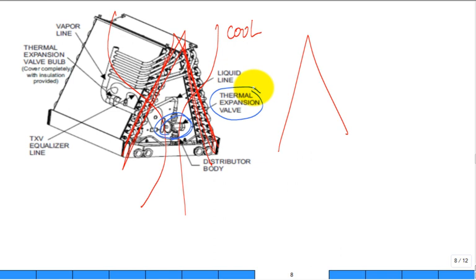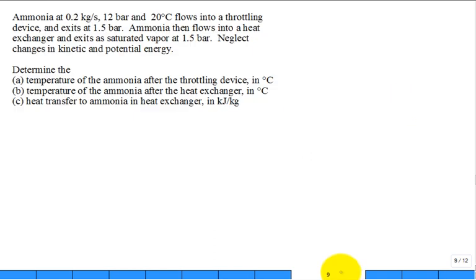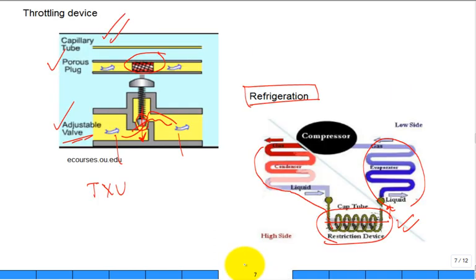Anybody work in shops, know what the air conditioning metering device is? Yeah. They have different ones. Some of them are really simple. The inline one, I got one upstairs, I forgot what its name is. A student gave it to me, as well as another one which is like an aluminum block. And it actually looks like a TXV. It has a little circular diaphragm on top that helps you lift a needle off of a small passageway to control the flow through it.